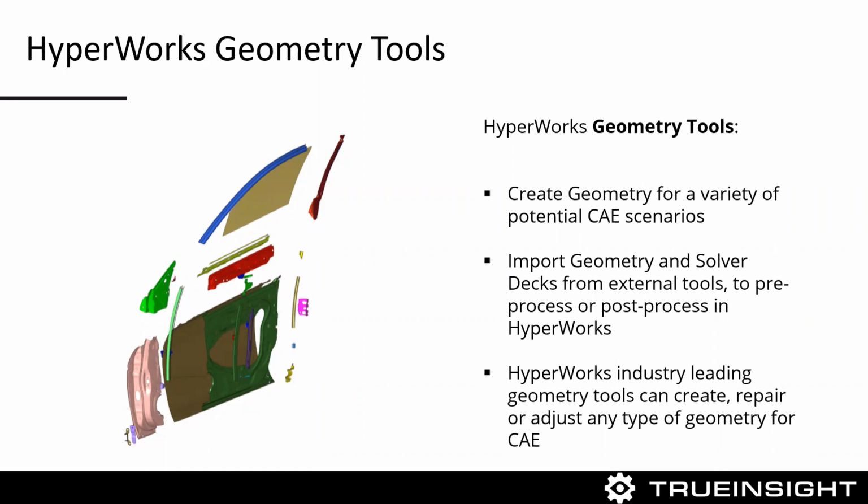The other application is that we have many customers coming from their own CAD platforms, CATIA, SolidWorks, et cetera, and I'll show you all those. We can import and bring in those different geometry models, assemblies, sub-assemblies, bodies, et cetera. The other really cool thing about our pre-processing tools within HyperWorks is that, obviously, Altair has powerful solvers and we can solve these cases with them, but like I already mentioned, you can pre-process our data. So say you want to utilize your current solver, you can generate the mesh, adjust your geometry, and then send it out to your own solver.